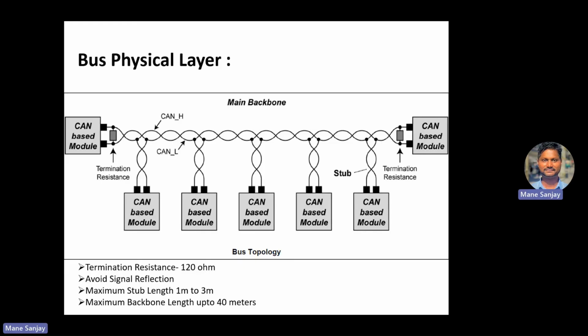But to put a right figure at a robust value, it is identified that 120 ohm is going to be close most of the time for the relatively large wires commonly used in the CAN protocol. That's why for CAN and RS485, the specification is officially 120 ohm. But unless you are going to a higher baud rate, the difference is small enough that you can use Cat5 for CAN with a 120 ohm termination resistance. So hope it is clear now why we are using the termination resistance of 120 ohm.